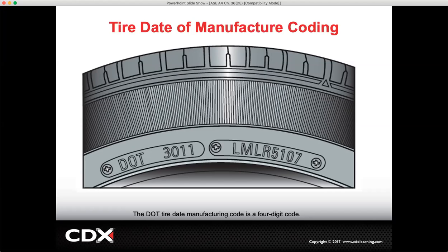Now here I have a tire with the DOT number, and I want to show you guys where exactly that code is. So normally on the tire itself, there's going to be 2 DOT numbers, stamped one on each side of the tire sidewall. So you're going to look for the longer DOT number, and then once you find it, you're going to go all the way to the end. So this number right here is what tells you the date of when the tire was manufactured. These letters over here are the plant code and all this regulation stuff. Over here is where you'll find the date itself.